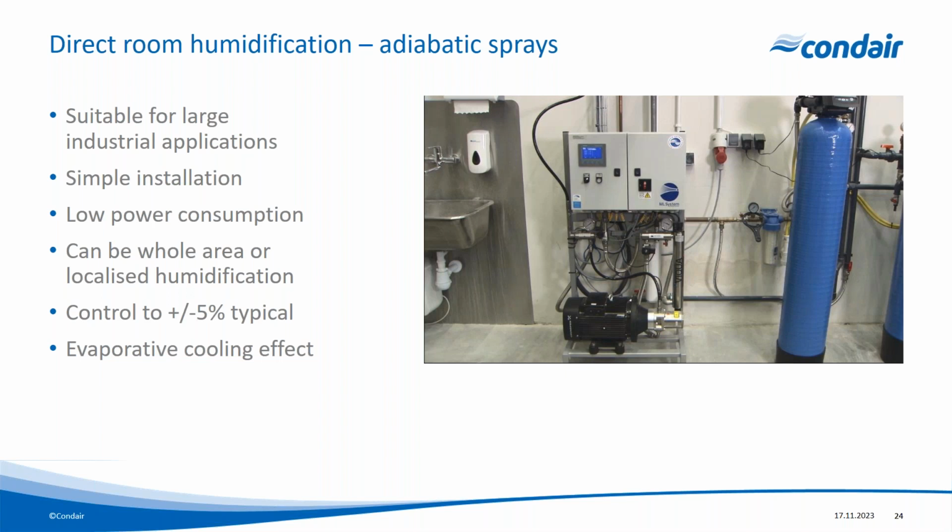And as the water is sprayed out through the nozzle, those minerals will go with the water. But when the water evaporates, those minerals will fall out into the space and we'll get dusting happen. And also, it will clog up the nozzles. So after a period of spraying, those nozzles will start to drip and start to clog. So we have to take the minerals out of the water before we spray it.